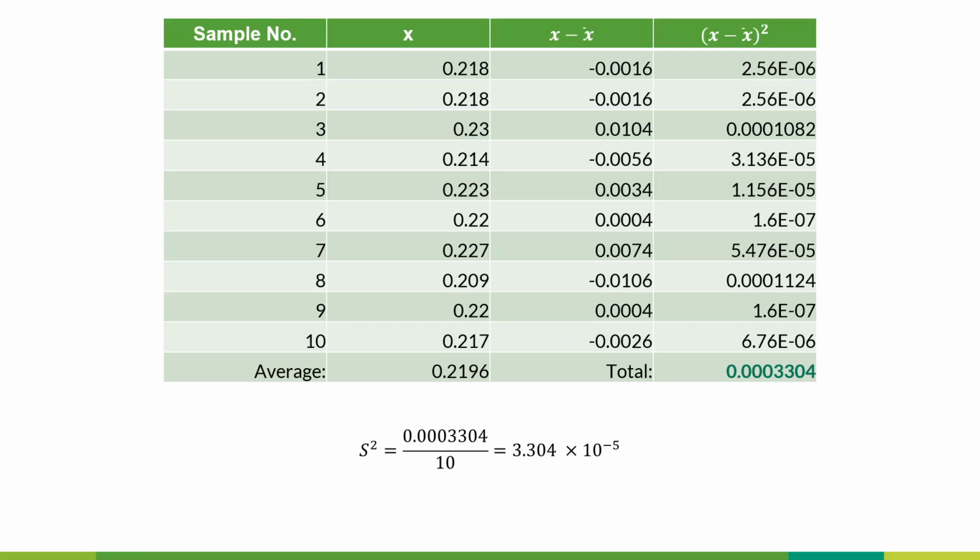We still do not know S0² and S∞². So for an unmixed solution, S0² is equal to P into (1 minus P), where P is the weight fraction at time t equal to 0. At time t equal to 0, you had 15 kgs of active compound and 85 kgs of your inert material.